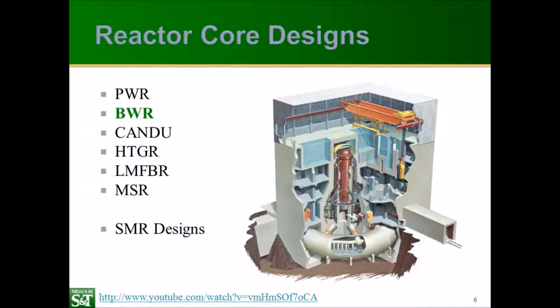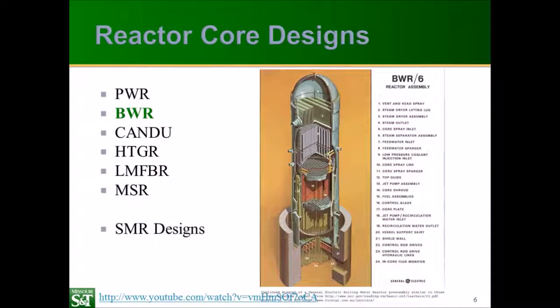And this is just an example of the actual layout of one of these BWRs. This is a Mark II BWR from General Electric, and you can see the distinctive upside-down light bulb shaped containment there. The reactor vessel itself has jet pumps that circulate the water, the coolant. And you have some mixing behavior, some flow and heat transfer behavior in the steam separator and the dryer.